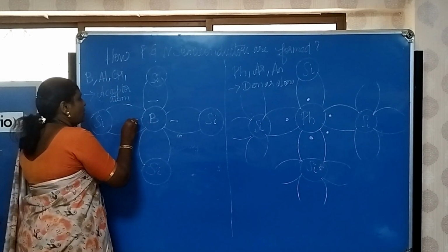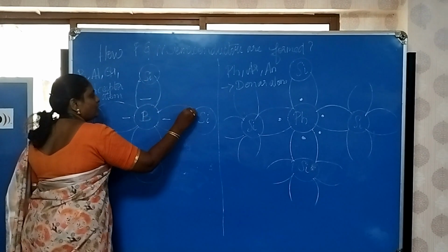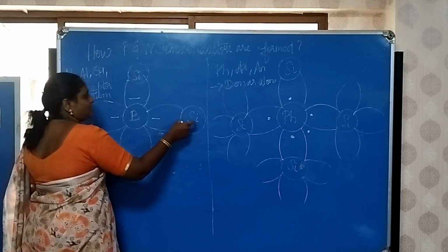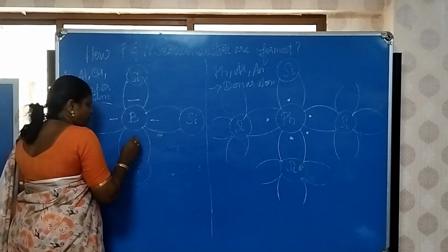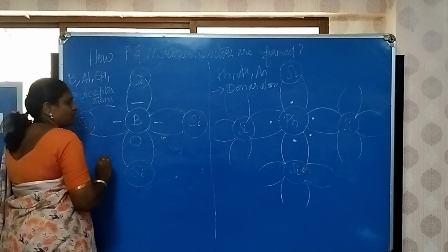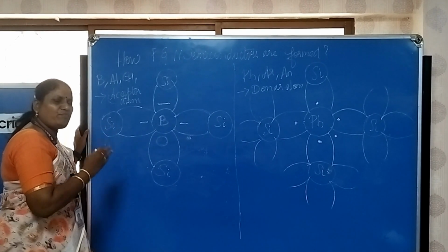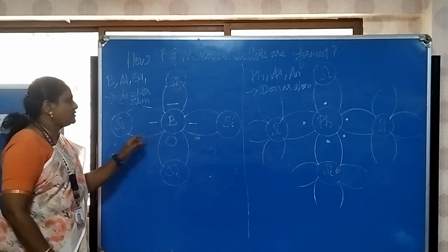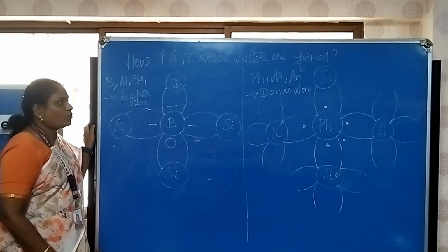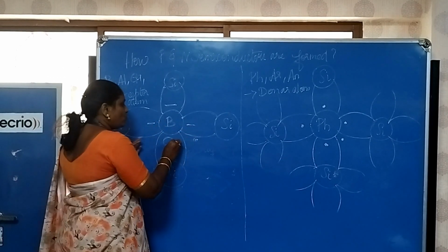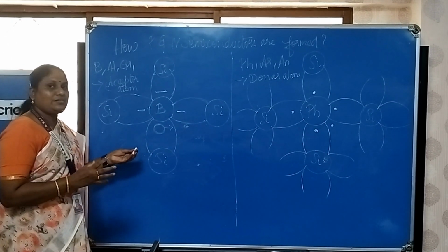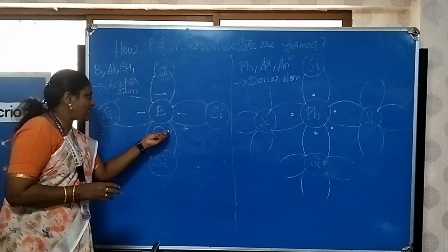So here we are all bonded together. We are adding this impurity, boron, to the pure semiconductor silicon. So if boron and silicon are bonded, a free hole will be created at the 4th bond. Likewise, if we are adding more doping, the number of holes will be more in the P-type semiconductor. So here, adding a trivalent impurity is called an acceptor atom.